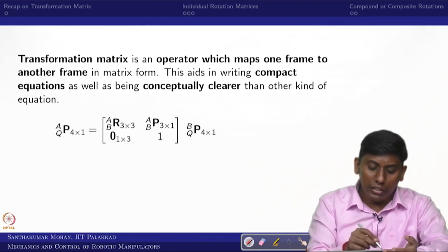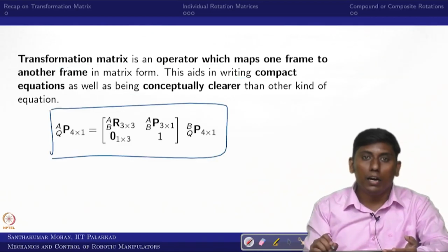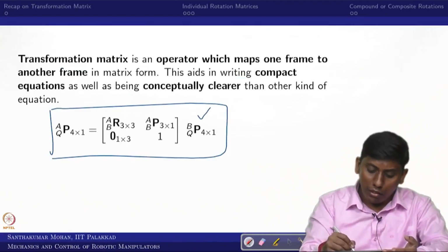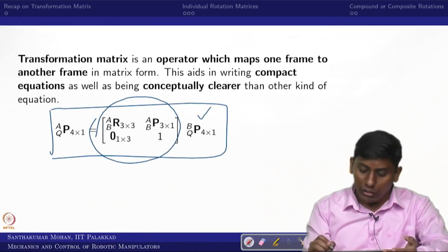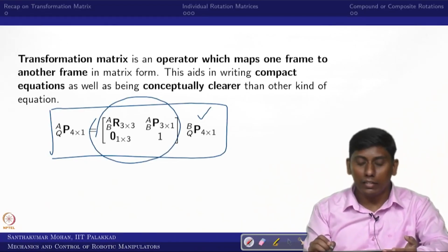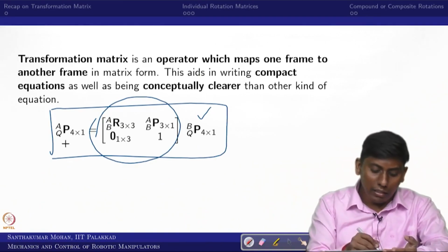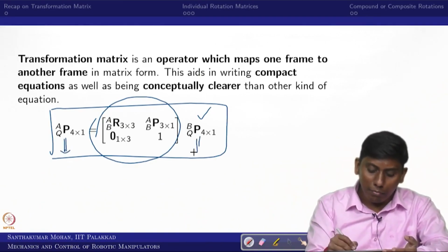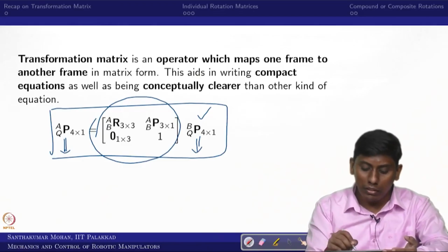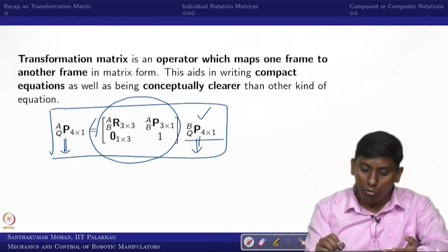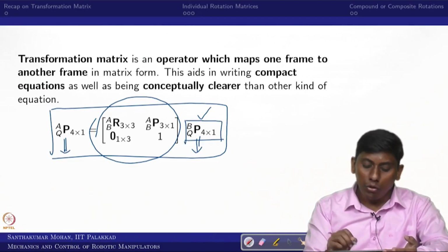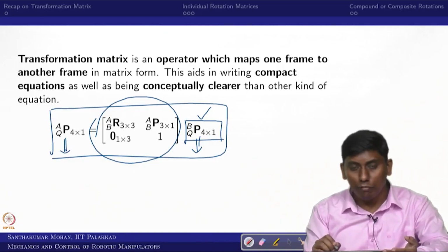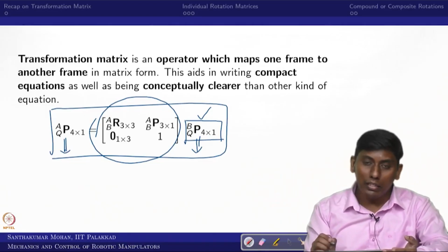Based on that, the position of q with respect to a, whereas the position of q with respect to b is given, and if we know the transformation matrix of b with respect to a, we can get the final result. Now the generalized position vector has been increased by one dimension. That is what we call the homogeneous coordinate or homogeneous position vector. Here we have added the scaling factor. For simplicity we take the scaling factor as 1, otherwise we can bring in the original scale.